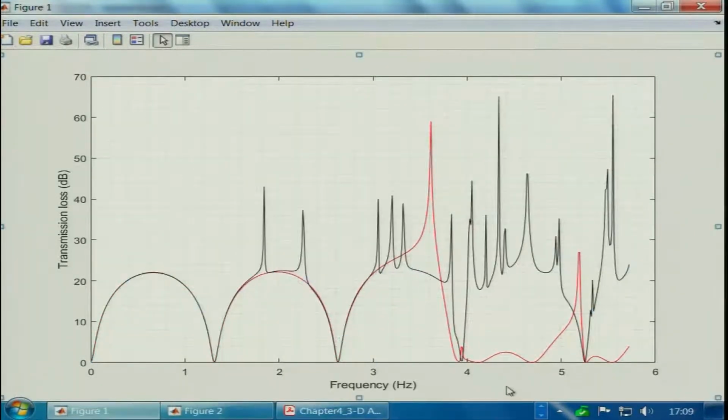This concentric chamber thing breaks down at k naught r naught equal to 3.83, which is basically the first radial mode frequency, but this particular case continues to do well even beyond this. The dome and trough continue to do well for a concentric inlet and an offset port located at the radial mode. Now, let us do something even more interesting.